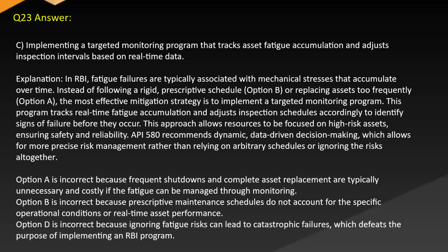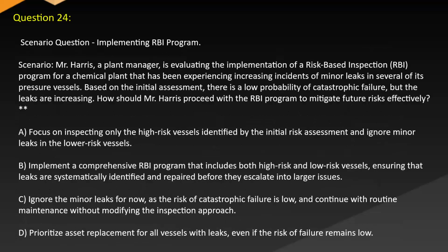Option B is incorrect because prescriptive maintenance schedules do not account for the specific operational conditions or real-time asset performance. Option D is incorrect because ignoring fatigue risks can lead to catastrophic failures, which defeats the purpose of implementing an RBI program.